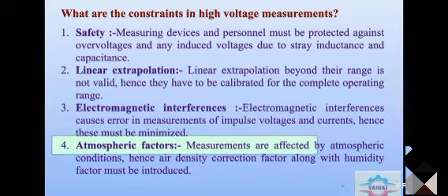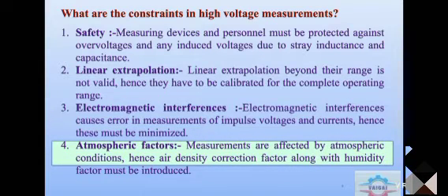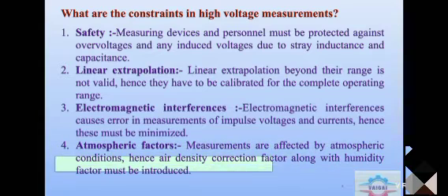And the next factor is atmospheric factors. That is, measurements are affected by atmospheric conditions. Due to weather conditions, it may be affected. Hence, air density correction factor along with humidity factor must be introduced for the high voltage measurement.